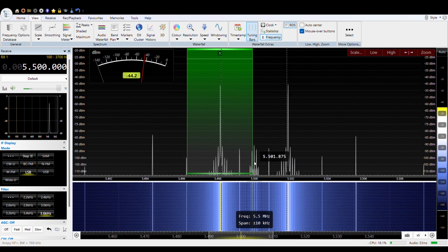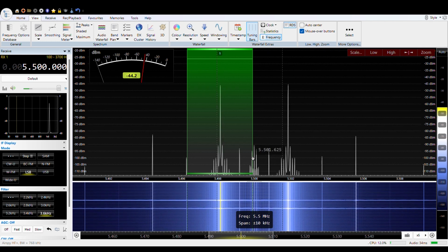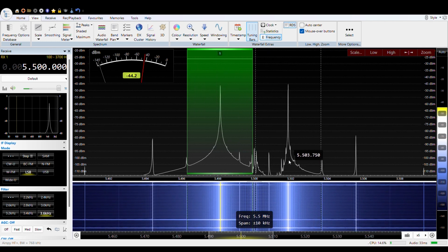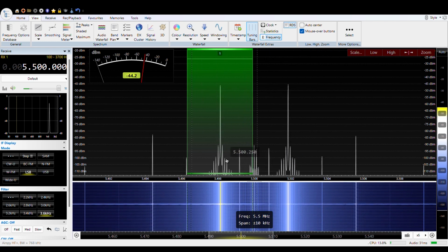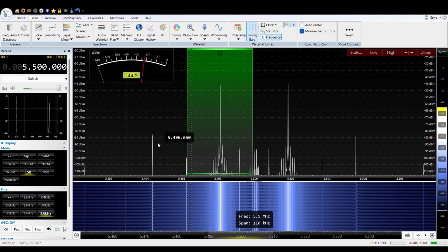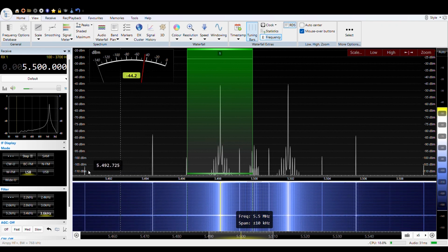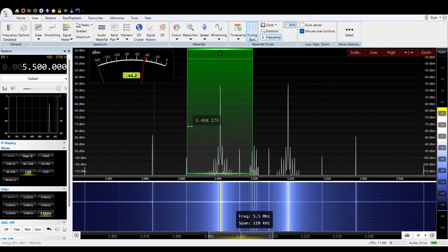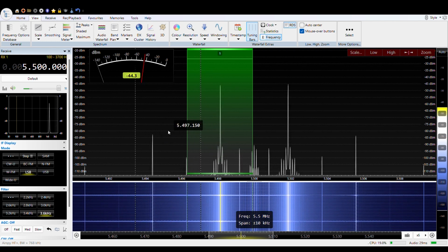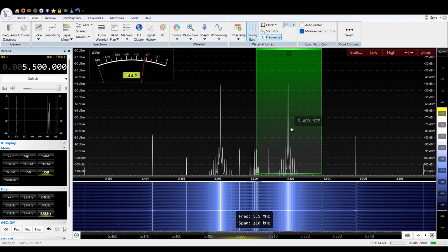And of course, there's no strong carrier. There's some artifacts here. I'm not sure we can trust that to say that that's carrier bleed through or not. And also this other garbage around each signal. I wouldn't read too much into that. And the other observation we can make, though, is that's the second harmonic, that's the third harmonic, that's the fourth kind of off screen, and then the fifth of the audio input. So that's showing up coming through. But again, that's going to get knocked out, of course, because my crystal filter is only going to take what's in this region right here.